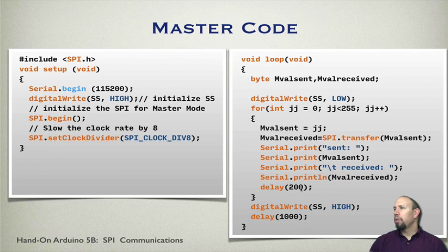And notice that we're not going to let it go high again until we've done all of this stuff. In other words, I know I'm going to be transmitting all this data, and then I'm going to pull the slave select high. Pulling it low and letting it go back high, it can be as long as you want in between there. So I pulled it low, and now I can send data.